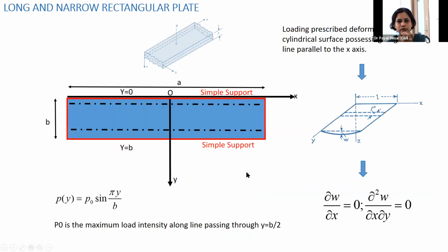Now this is how to solve this problem. So you can take the long rectangular plate. You may simplify it, a plate like a one-way slab. All of you have analyzed and designed a one-way slab, where the bending happens in the cylindrical shape. And then finally you end up analyzing only the bending in this direction, right? That is the primary bending in this direction. In the longer direction, there won't be much effect. So what we do is we can simplify our differential equation.